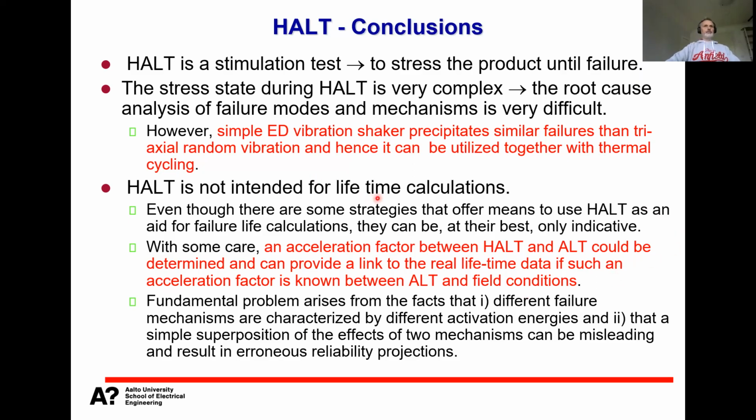Basically, HALT is not intended for lifetime calculations. We shouldn't use HALT for estimating lifetime, but if you Google it, you see a certain number of papers claiming that they did HALT testing and verified the reliability of their product. This is based on using different types of tests, accelerated tests and highly accelerated tests, compared to normal use conditions, and trying to understand the acceleration factor between those.